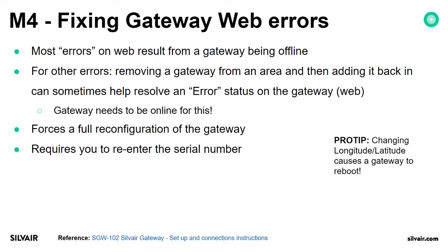If someone disconnects the gateway during commissioning, when you add the gateway, it may cause problems. It may also cause problems if you want to apply different schedules and the gateway is offline. It will not work properly.